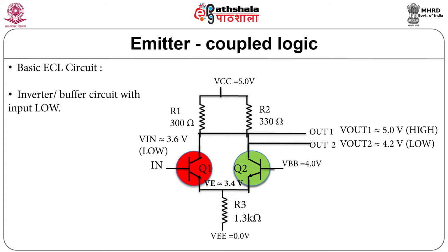That is, the output is 1 if Vout1 minus Vout2 is greater than 0, and it is 0 if Vout1 minus Vout2 is less than 0. It is possible to build input circuits with 2 wires per logic input that define the logical signal value in this way. These are called differential inputs.